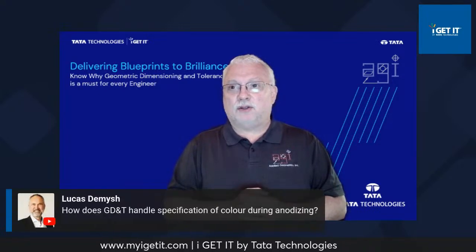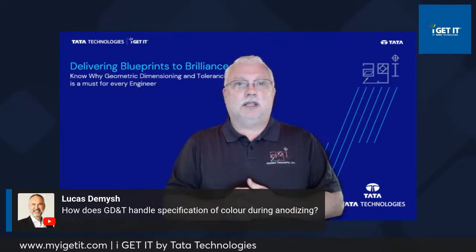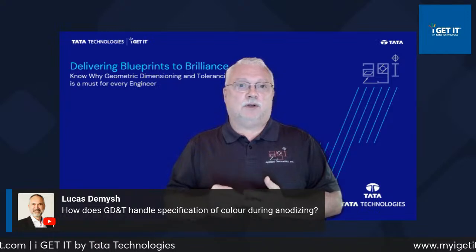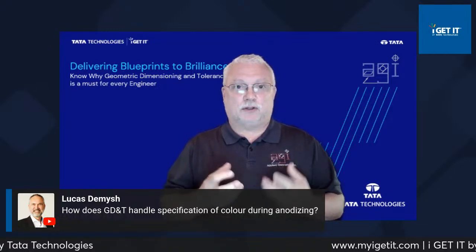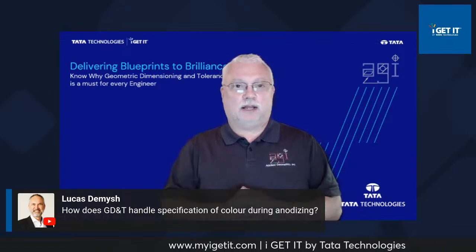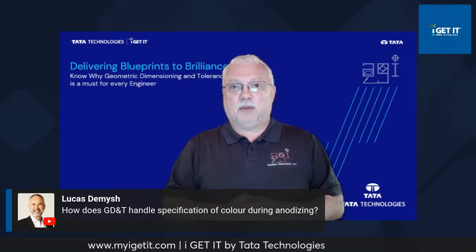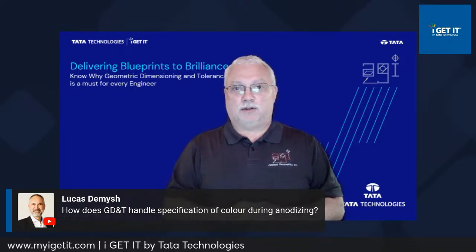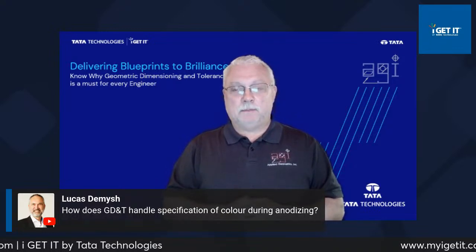Somebody just asked the question, how does GD&T handle color during anodizing? GD&T is about dimensions and tolerances of physical dimensions. So it does not address color or anything like that. That would have to be covered under other standards other than Y14.5.